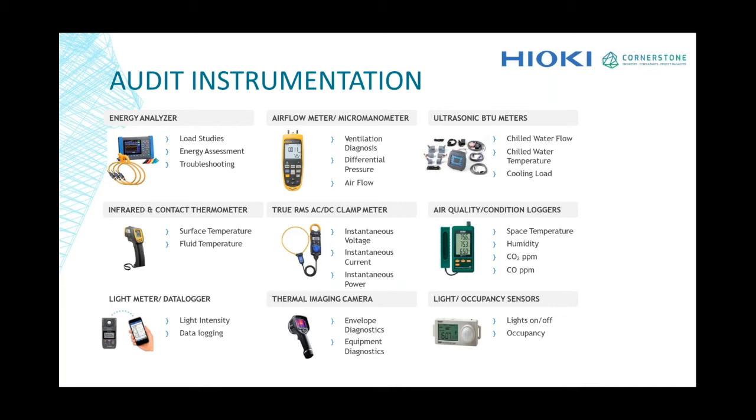Then we have different airflow measurements taken for FAHU, fans, air handling units, FCUs. So that would also be required to be taken, to make some performance studies. In terms of pump water flow as well as chiller flows, we use ultrasonic meters to understand what the chilled water flows across the buildings and the lines are. That is taken into consideration.